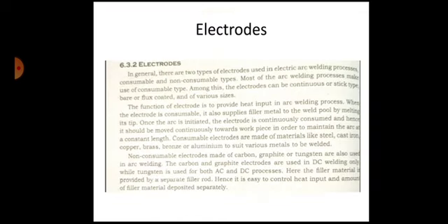Okay. Then electrodes, but before going to electrodes, the DC arc welding is generally preferred because it provides better control of heat input. Mostly we use DC arc welding because the control is easy. In DC arc welding, about 70% of heat is liberated near the positive terminal, that is anode.